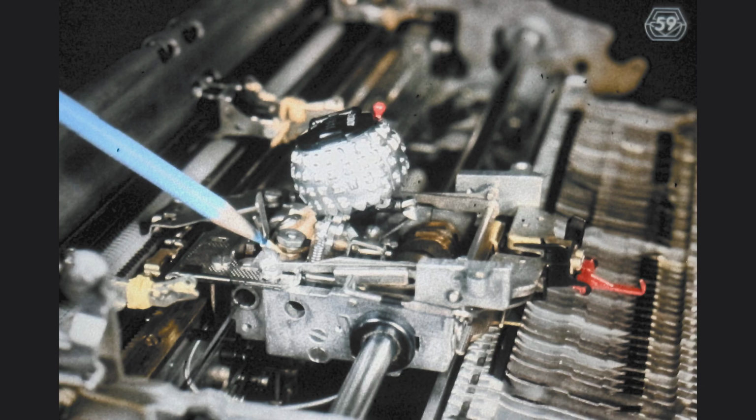On recent level machines, and assuming that the detent actuating lever is in its original shape, the vertical position of the actuating lever has very little, if any, effect on the vertical position of the tilt detent, and therefore on the rest position of the rotate detent. The reason is that the edge of the tilt detent, which contacts the detent actuator lever, is almost perfectly vertical when the machine is at rest, and the detents are kept disengaged.